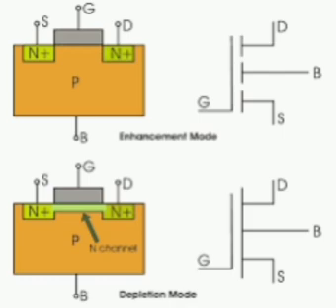IF means the majority carrier current, the diffusion current. I naught means drift current, the reverse saturation current. I naught doubles for every 10 degrees centigrade rise in temperature. I naught of T2 equal to I naught of T1 into 2 power (T2 minus T1) by 10. I naught of T2 means reverse saturation current at temperature T2, I naught of T1 means reverse saturation current at temperature T1, T2 greater than T1. I naught depends on temperature and is minority carrier current. IF, forward diode current, is independent of temperature.